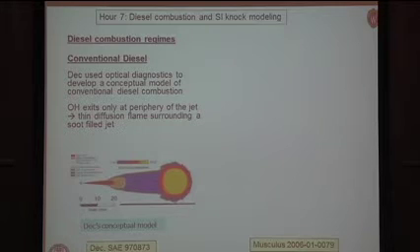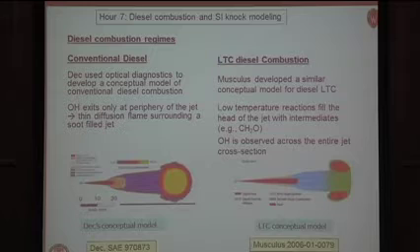as we already know. If one operates with low temperature combustion, in other words, like that PCCI we were talking about, things change a little bit. And Mark Musculus at Sandia has proposed a conceptual model. In this case, here's our fuel again. The light brown here is vapor that's being produced from the liquid fuel. And now this blue region represents basically intermediate species, such as formaldehyde, that characterize the first stage of combustion.